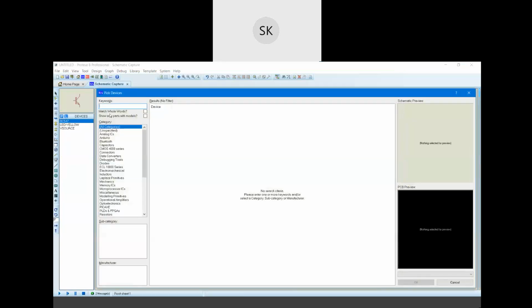So to detect the fire, the sensor relies on two qualities of fire, right. One quality is its radiation. Fire is emitting infrared radiations, and another is its temperature. When there is fire, absolutely the temperature is going to be raised. So we are using a thermistor. I think you might have performed this project in your PPL also, but we know what we were actually doing. We were just taking it from elsewhere and modifying it. So if it comes to designing by ourselves, this is how we can proceed to design it.